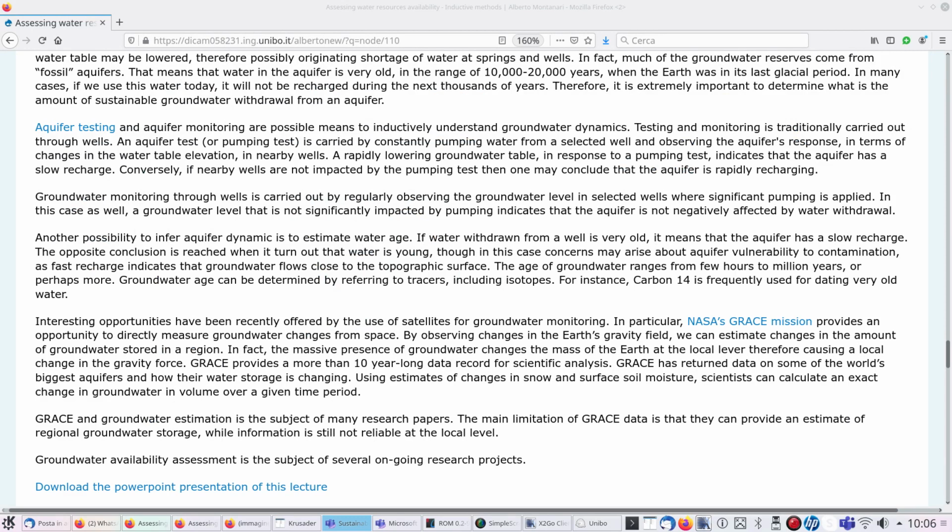So there is a question: are the permeable layers variable just spatially or also in time? Now, usually, in a phreatic aquifer, which is confined only below, you have changes in space of the medium, and then you may have changes in time of the water content and water level. But the medium, in general, usually doesn't change in time, unless there are earthquakes or something like that.